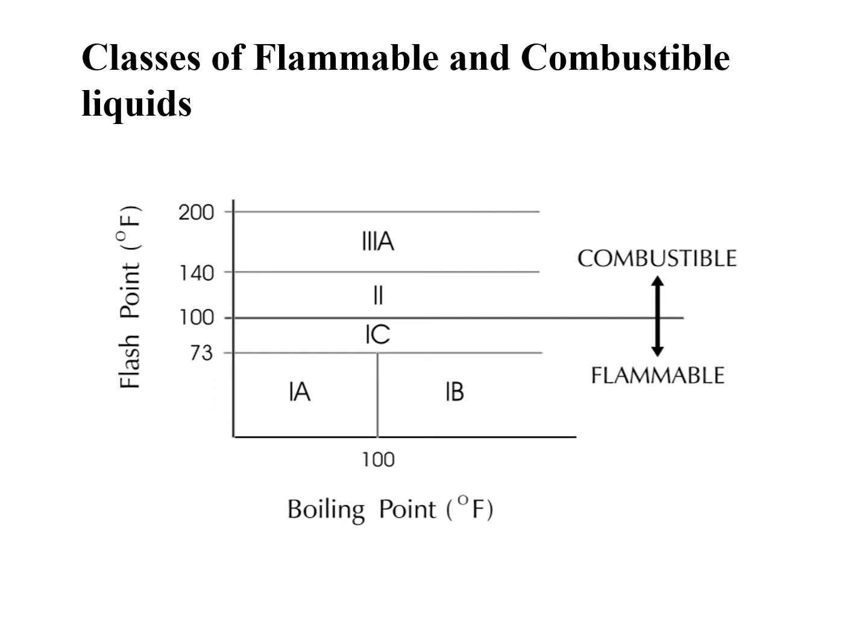Here in this table you can see the flash point temperatures and boiling point temperatures, giving more clarity about these combustible as well as flammable liquids. Of course, flammables have a single class, like 1A and 1B, while combustibles have two classes, like the 1st, 2nd and 3rd, right? These are according to their temperatures, so this is just more explanation about the temperature range divisions.